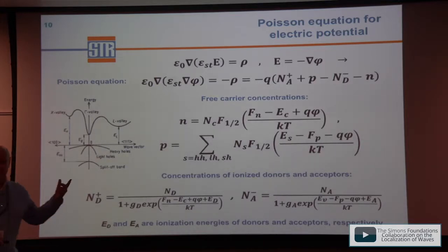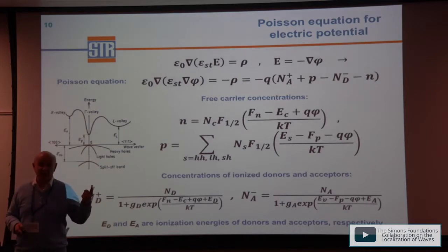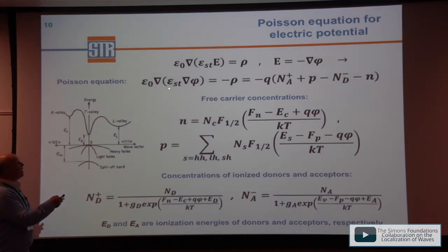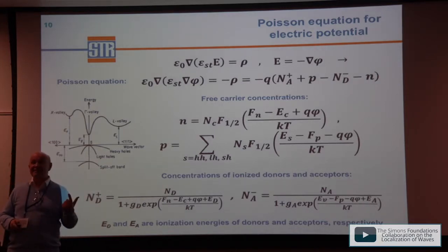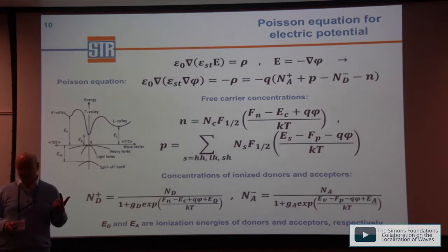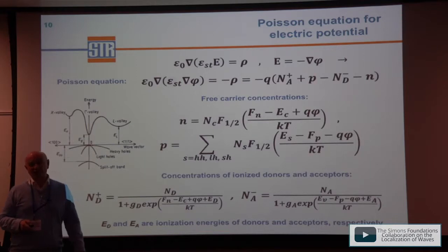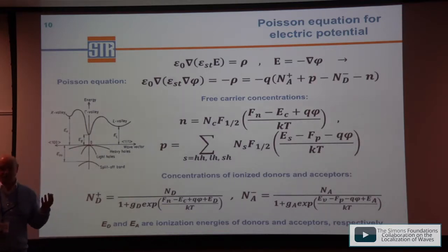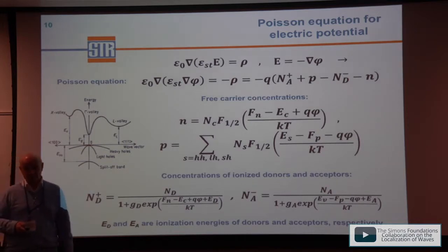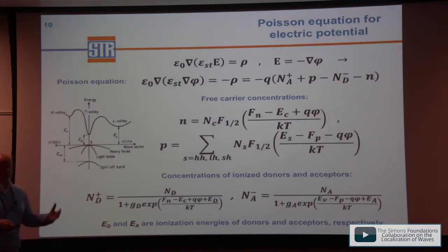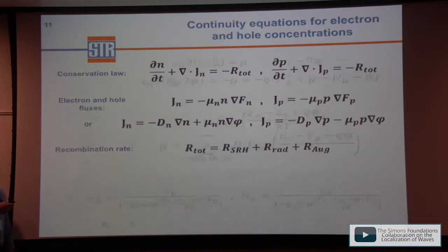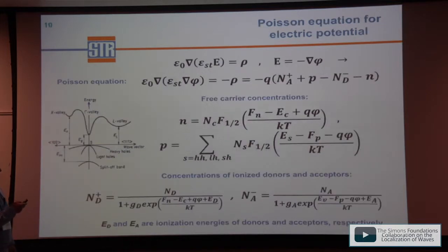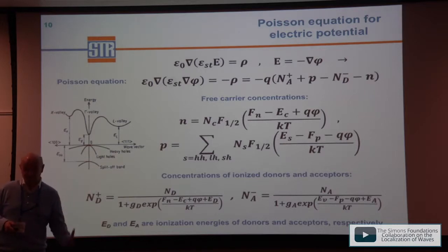This is the electric constant. It is a fundamental constant. And here epsilon is the static dielectric constant. Do you get it from experiments? It is usually taken from experiments. So this is a material constant which is known for most semiconductors. And in the case of conventional III-Vs, the static dielectric constant is a real scalar value.